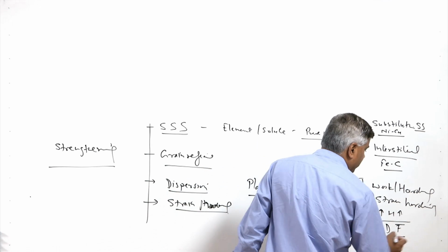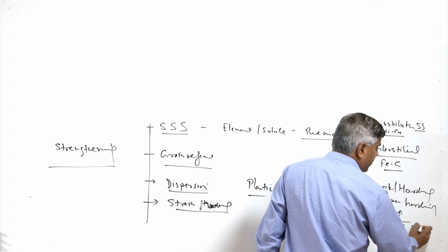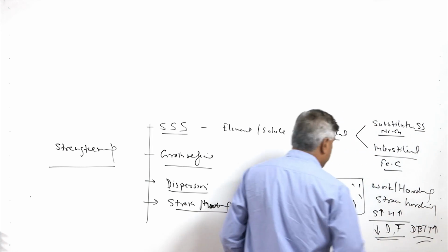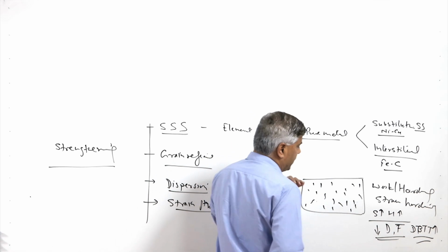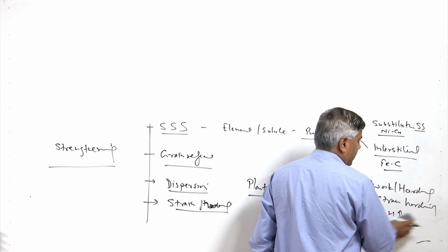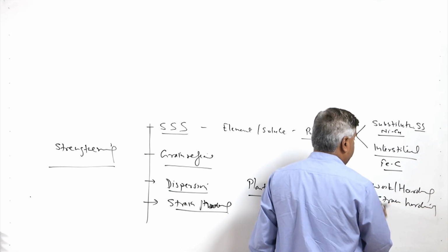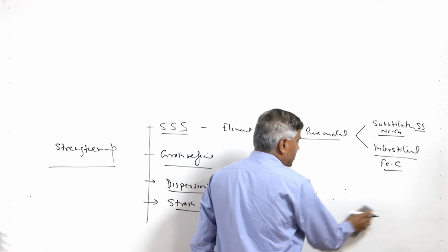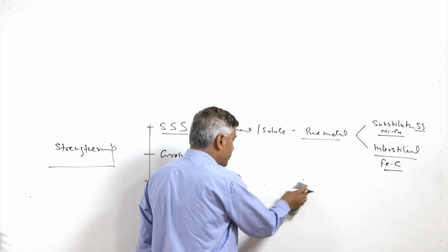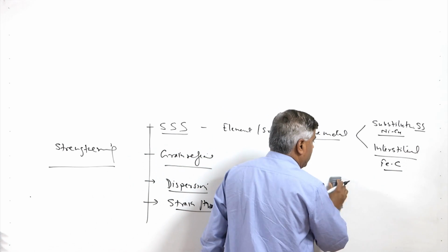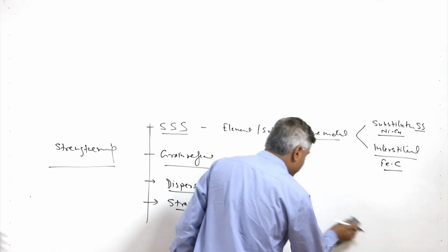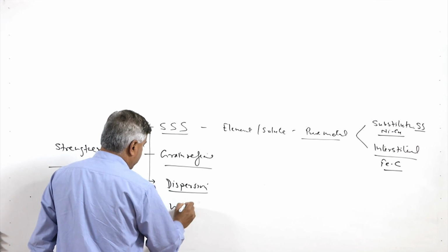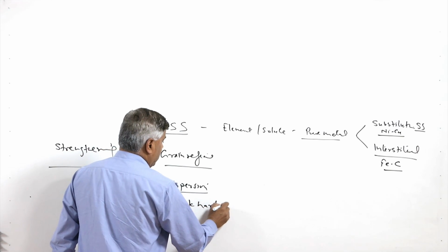Also, the ductile to brittle transition temperature, DBTT, is increased when cold working, the plastic deformation for strain hardening or work hardening, is applied. The ductile to brittle transition temperature is the temperature at which there is a sharp drop in the toughness of the material, below which it tends to behave more like a brittle material. So, work hardening or strain hardening is another approach.